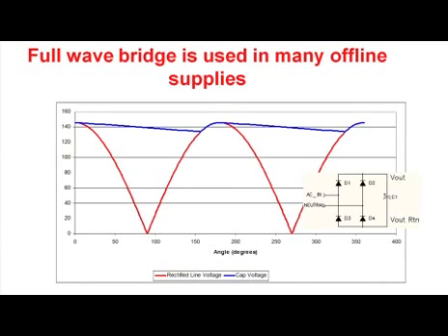The first one is a full-wave bridge rectifier, as shown in our little schematic over here on the right of the slide. It consists of 4 diodes, and as the input voltage is applied to the circuit, when the input voltage exceeds the voltage on the capacitor, the diodes conduct over this period here. And then at some point, the input voltage is going to fall below the capacitor voltage, and the capacitor itself will hold up the input voltage. You can imagine the slope of this line changes as the value of the capacitor changes, and that also changes the conduction angle.